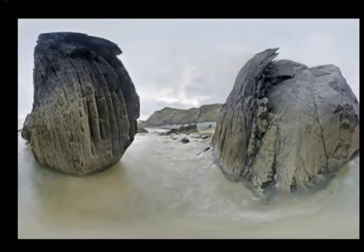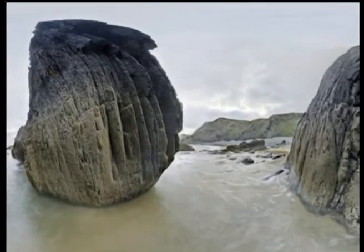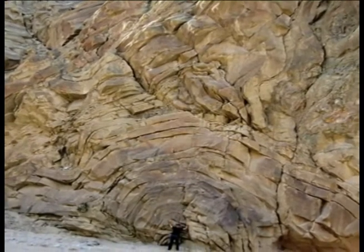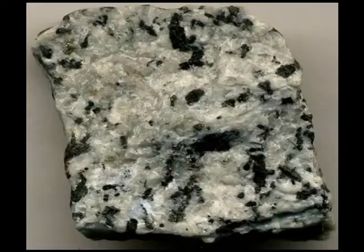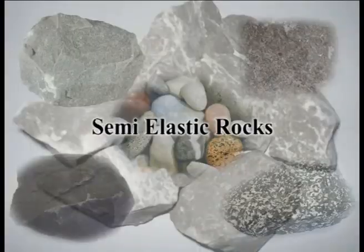Quasi-elastic rocks are rocks in which the stress-strain relationship is expressed by almost a straight line till the point of failure. Such rocks include massive, densely packed, uniformly structured varieties of igneous, sedimentary and metamorphic groups such as syenites, diorites, dolerites, gabbros, basalts and quartzites.